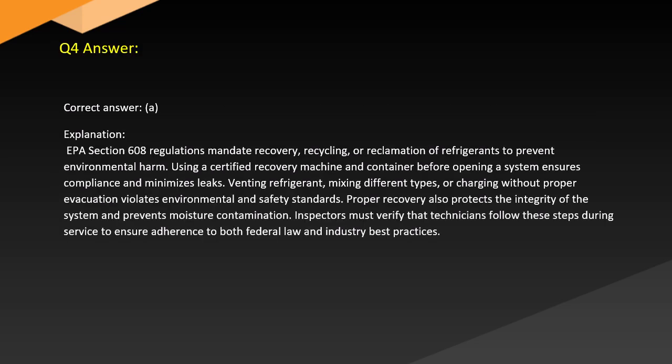Answer. Correct answer: A. Explanation. EPA Section 608 regulations mandate recovery, recycling, or reclamation of refrigerants to prevent environmental harm, using a certified recovery machine and container before opening a system. This ensures compliance and minimizes leaks.